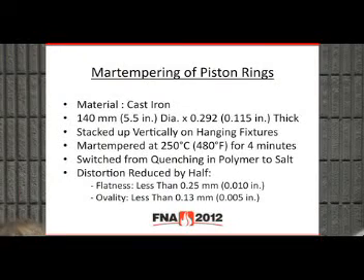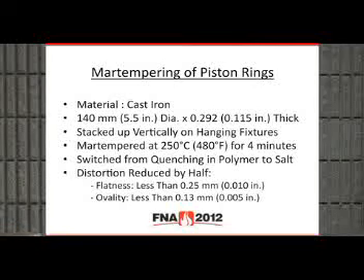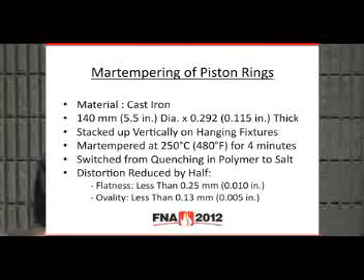Another example is martempering of a piston ring made of cast iron. In this particular case, it was martempered at 480 degrees for 4 minutes, and by switching from polymer to salt, the distortion was reduced by nearly half.